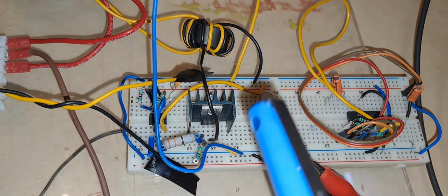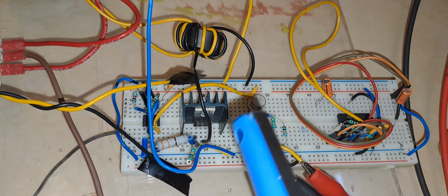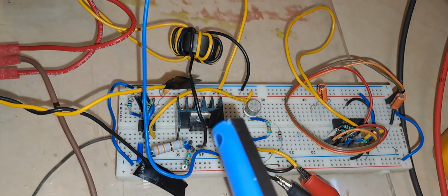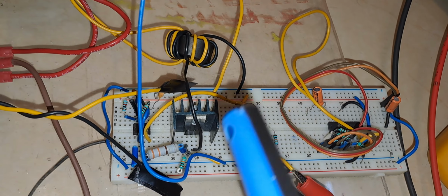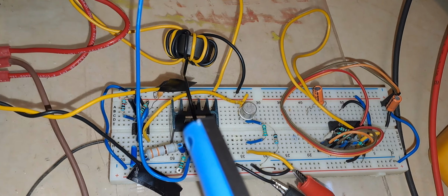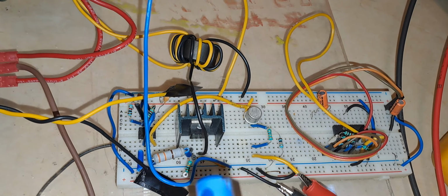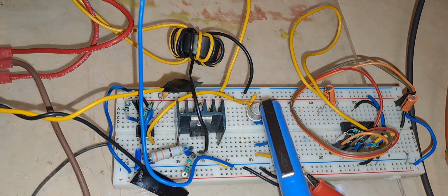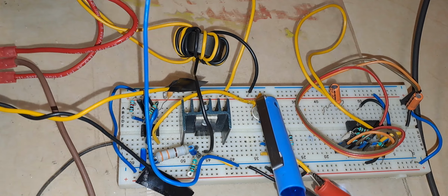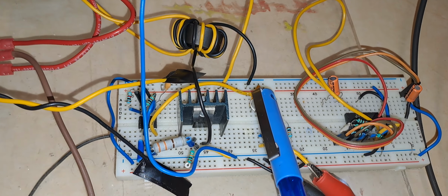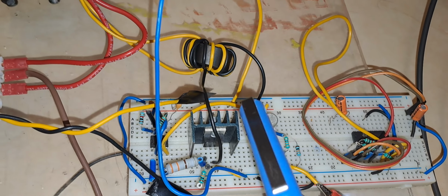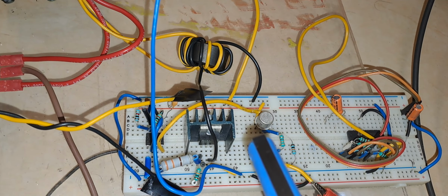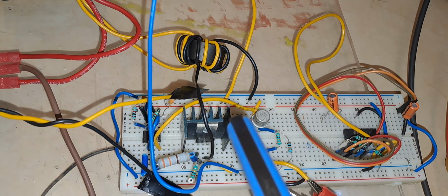So this is my oscillator. My oscillator is supposed to oscillate at a frequency of 48 kHz, and I am mixing a square wave of 50 Hz with this oscillator at pin number 4, the reset pin. You can see this is the transistor. At the base of this transistor I am feeding a 50 Hz signal, and as a result the 48 kHz signal is a pulsed 50 Hz signal.